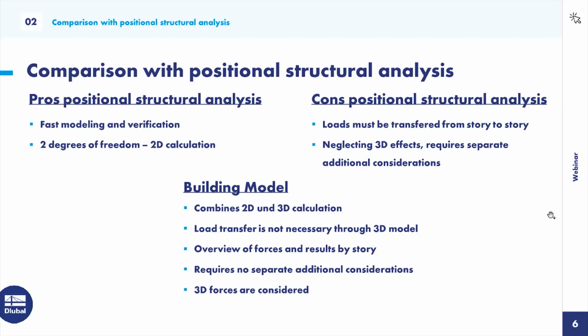Okay, another con is that the 2D calculation neglects 3D effects, and for example some forces, let's say torsional moments, and you also need separate additional considerations or additional checks which are for the whole building. And yeah, now to the building model.